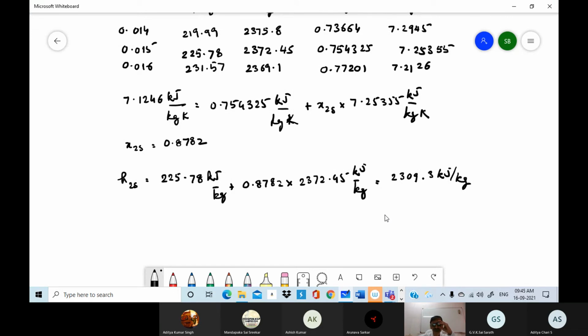So unlike a nozzle where the idea was to get a high velocity, so the cross section areas etc. are designed in such a way that you get a high velocity at the exit. In a turbine, it's not done that way because the main idea is to get work output. So in a turbine, usually we assume that the velocity at inlet and velocity at exit are comparable, so changes in kinetic energy and potential energy can be neglected.